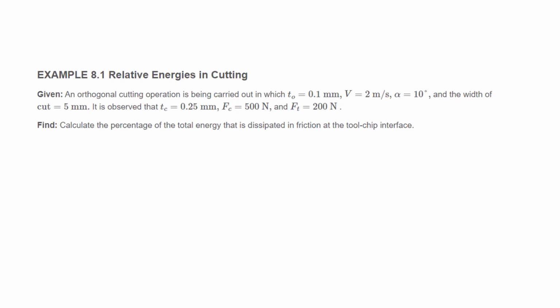Yeah. So that's the reason T0 multiplied by my V, the cutting speed in this direction, must be equal to the chip thickness TC multiplied by the chip speed. Definitely we should have time t here, but because both sides contain the time t, we just cross it out.